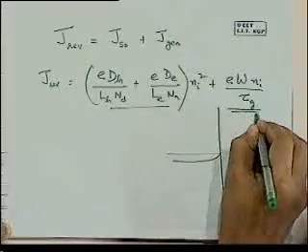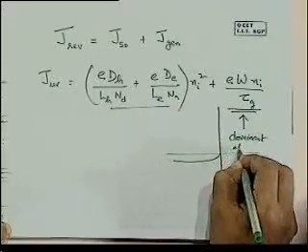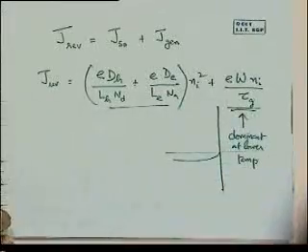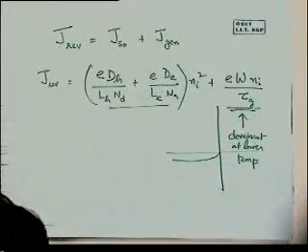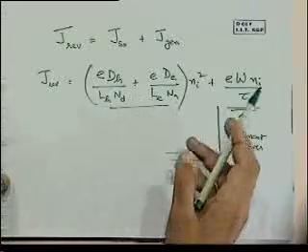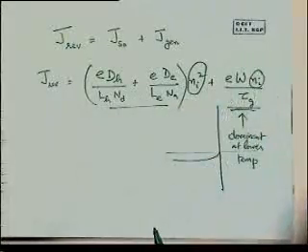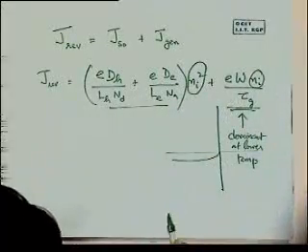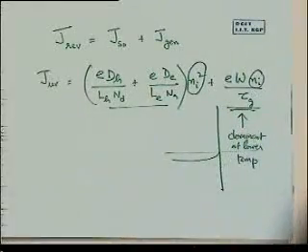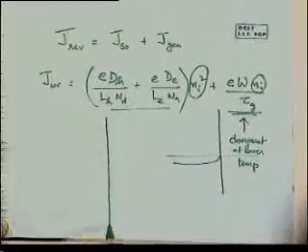This term here is dominant at lower temperatures. Diffusion, all that becomes rather small. And remember, in both of these, it is related to this n_i and n_i squared that we have in both of these terms. So at lower temperatures, we will see a domination due to thermal generation in the space charge layer. So what about this curve I just started plotting? We can plot it.